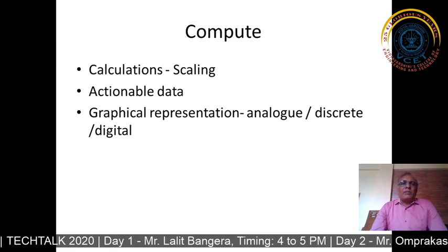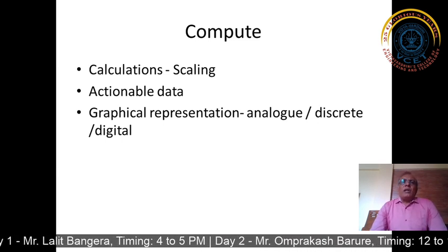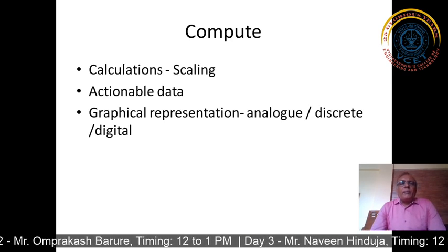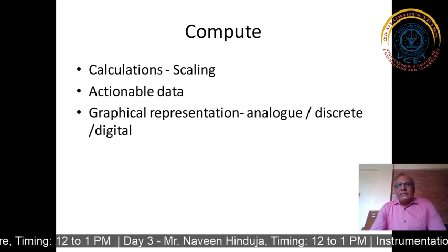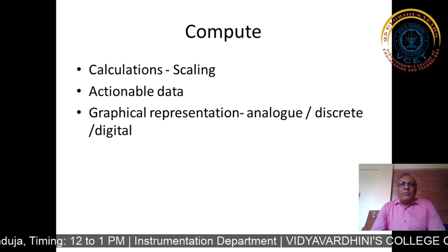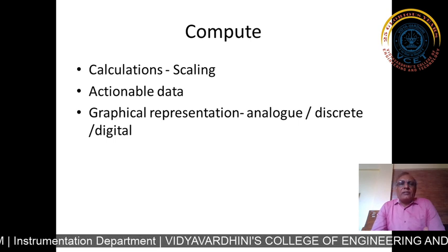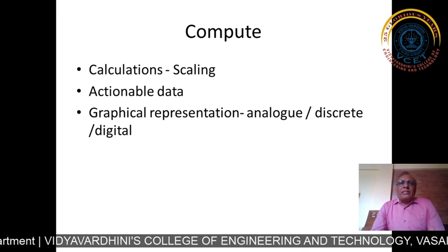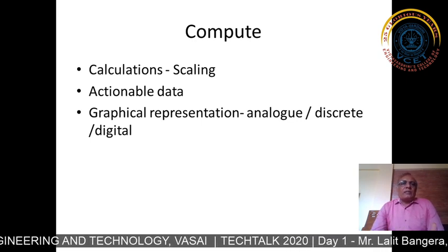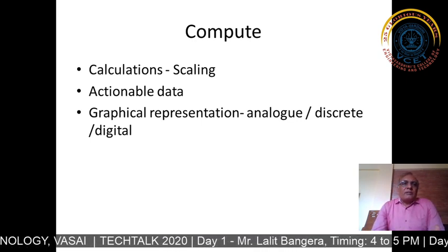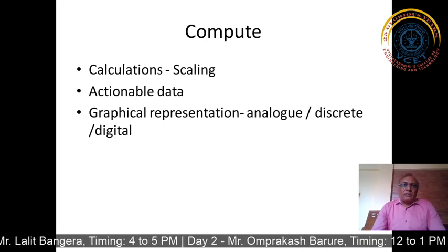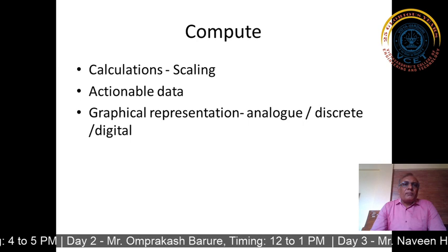And what do you mean by compute? This is perhaps a little bit new to some students. Computation is what? We need some calculations. We need some maths, man. Where? For scaling. Scaling means what? What I get as the final signal is a voltage. Now that voltage has to be converted into degree Celsius or degree Fahrenheit. This is called scaling. How much voltage should correspond to how much temperature? That is called scaling or calibration. Right? Here we need some calculations. Now who will do those calculations? The automation system will do that.